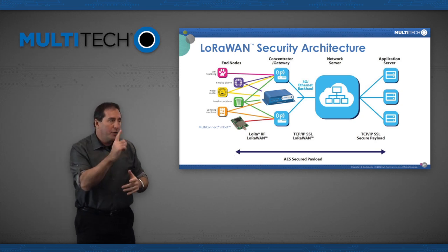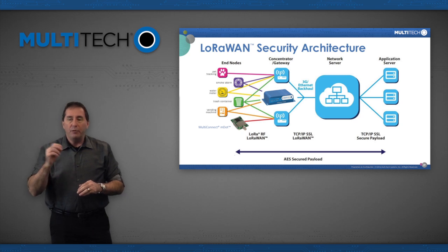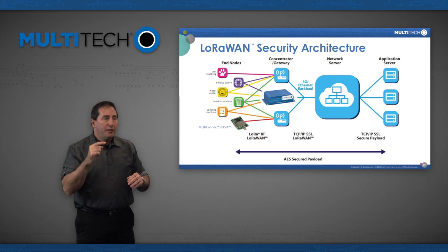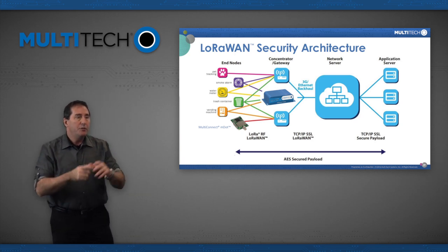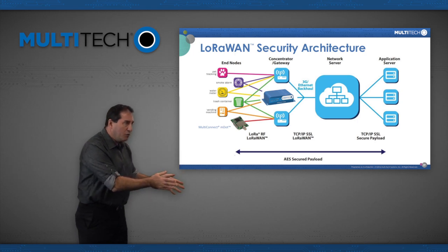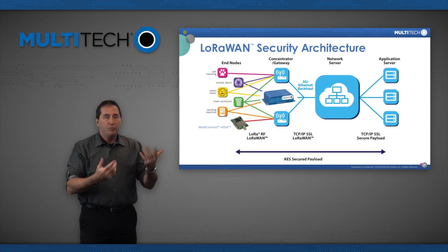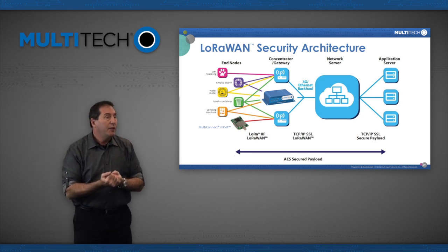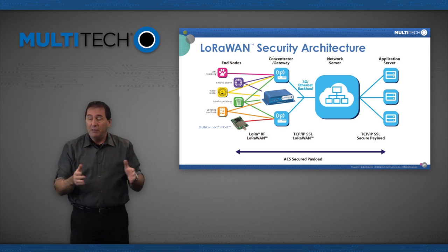And there's one other quick thing I'll mention about keys. This would all not be very good if these keys stayed alive or stayed in use for long periods of time. So the original, like today's LoRa network until 1.1 comes out, you do a join, you could go years without rejoining the network. That means your key would be the same because it's a session-based key.